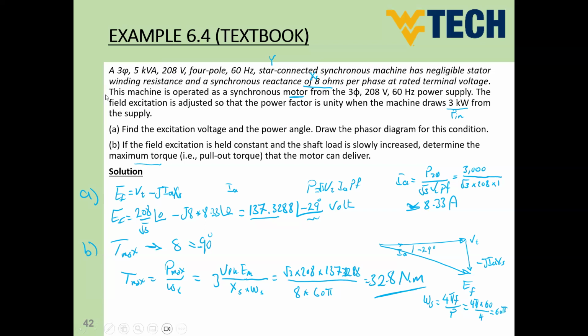Okay, guys. So this is one example, like an application for our synchronous motor. And we could see here how the machine can work at normal excitation. So it's not absorbing any reactive power or not delivering any reactive power. And at the same time, it's driving a certain load. Again, this is not a preferred case in industry because once you have the motor, you should get the benefit of providing reactive power to the grid. So this would help a lot the surrounding loads in order to improve the overall power factor of your factory.